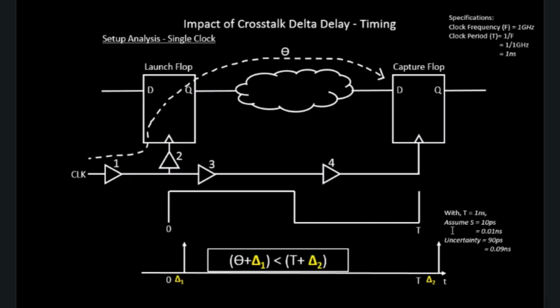Also, at every clock cycle, this clock edge is supposed to arrive exactly at t, but it might arrive somewhere before t or somewhere after t. In the same flop, when it receives multiple clock edges, the same edge might arrive at t, or beyond t, or before t, again because of the variation on the chip. All these things have to be accounted for, and uncertainty helps us calculate that. There are other ways, where on-chip variations and derates come in. We'll talk about that in a separate section.